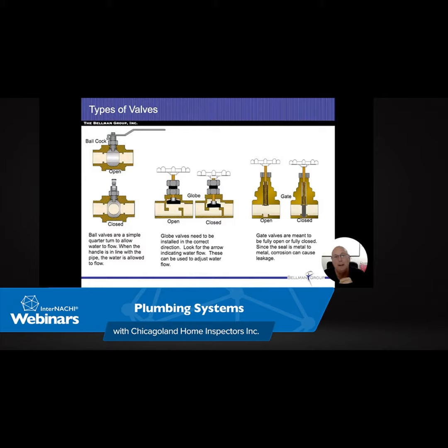The lower the pressure inside that pipe will cause that valve to open more and let in additional fresh air, slowing the heat speed down until it gets to that happy medium. So we get that flame or that heat speed going through the baffles and the vent and the flue. We get that all through that barometric damper that opens and closes.